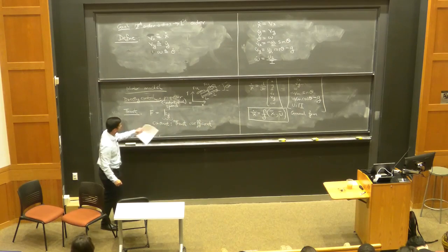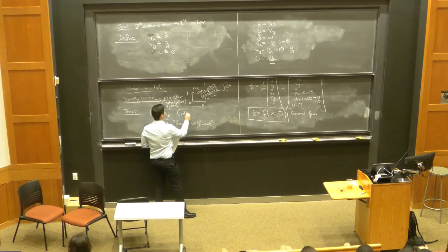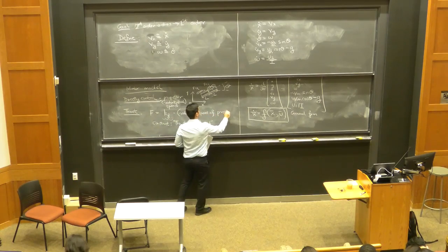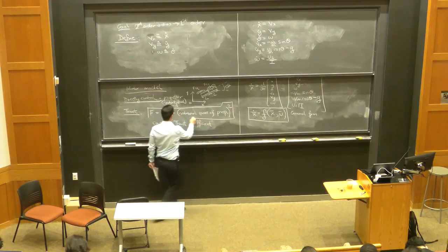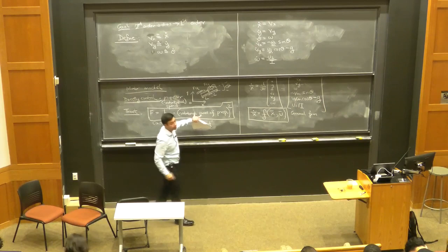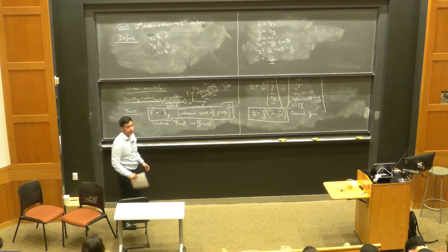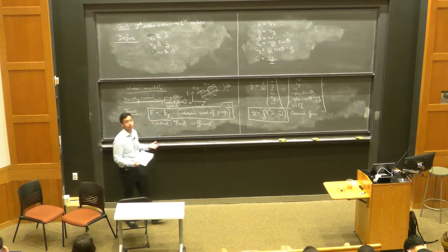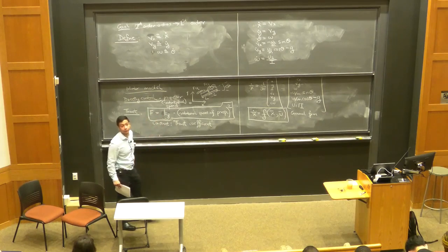So the thrust force is this constant multiplied by the control input, which is the rotational speed of the propeller squared. The thrust force is proportional to the rotation speed of the propeller squared, and the proportionality constant, Kf, we're giving the name the thrust coefficient. The particular value of this coefficient depends on the geometry of the propeller. If you change the size, for instance if you make it bigger, you might intuitively think that Kf increases. But the specific proportionality constant depends on exactly the geometry of the propeller.